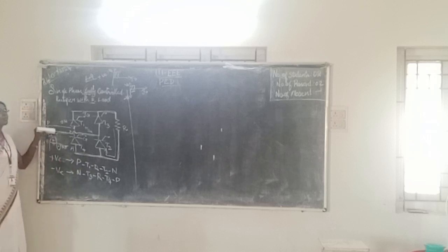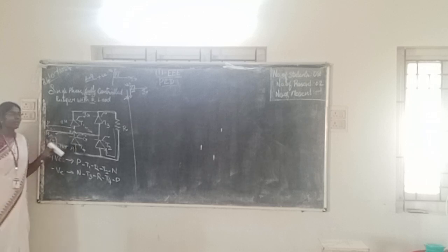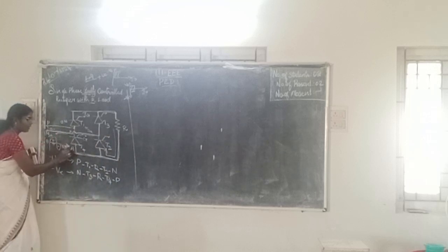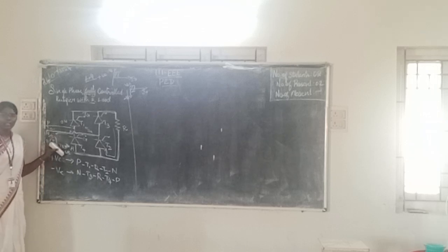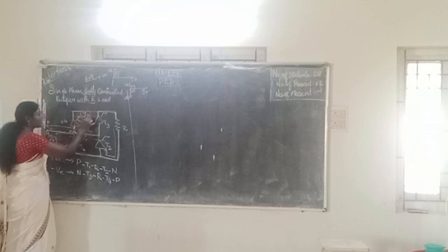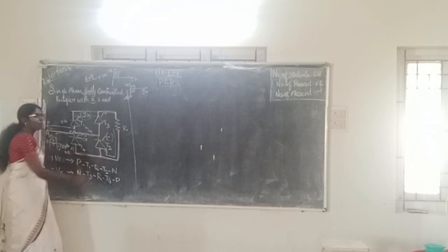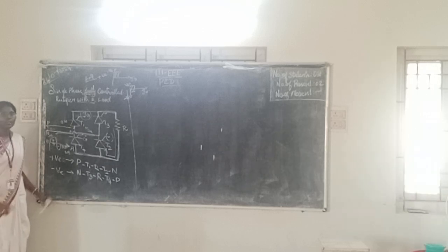This process will be successful only when both thyristors turn on at the same time. Everything is happening with respect to time t, and I have drawn this graph with respect to time t. So only if the triggering pulse which I am giving for T1 and the triggering pulse which I am giving over here for T2 remain the same will this operation be successful.